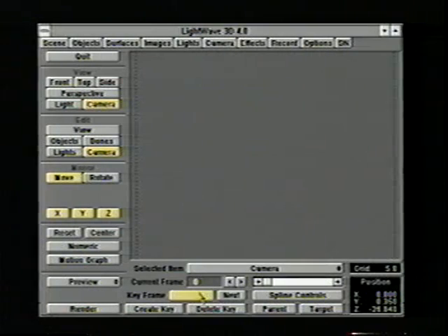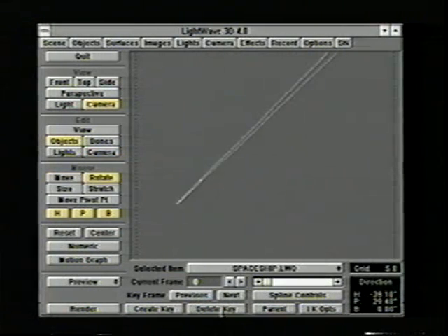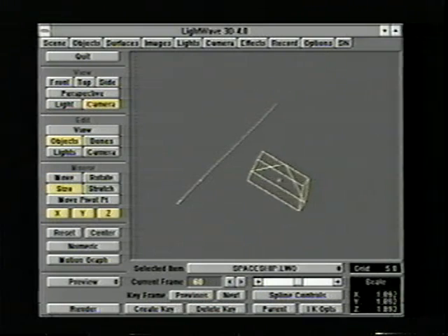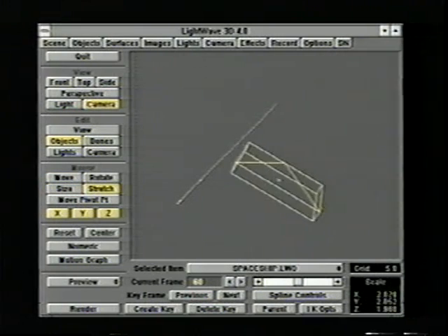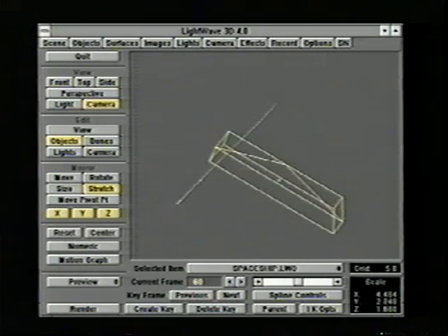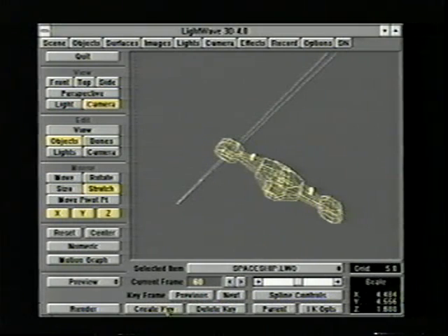Okay, well, you can add other keyframes. Let's select Objects, go to the next frame. Let's say instead of this location I wanted it over here instead. All I have to do is move it. If I want to size it out at this point, maybe stretch it along the x-axis or the y, give it some weird shape, I can do that, recreate the key.